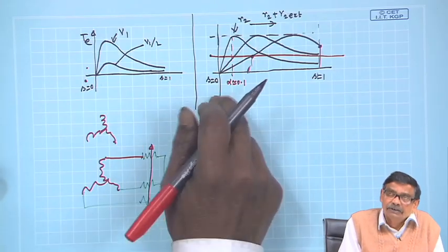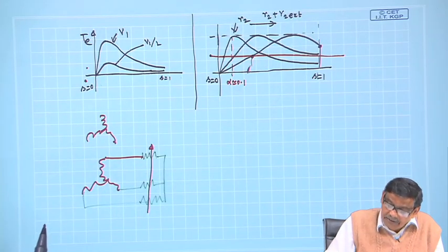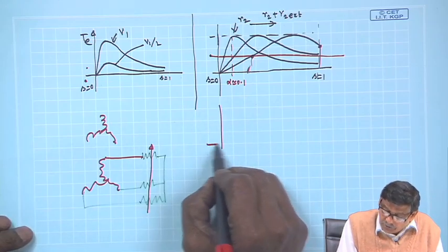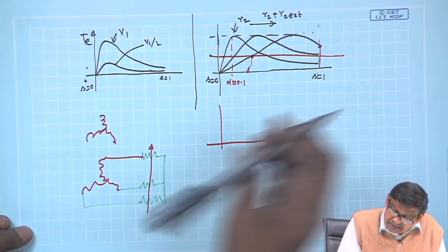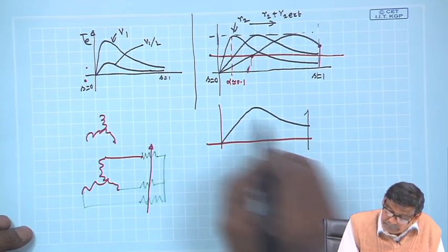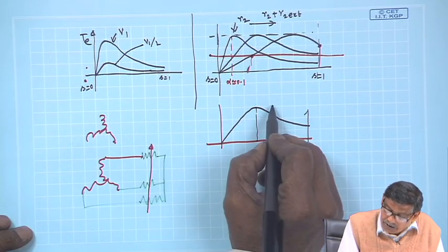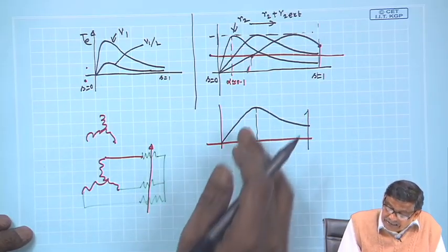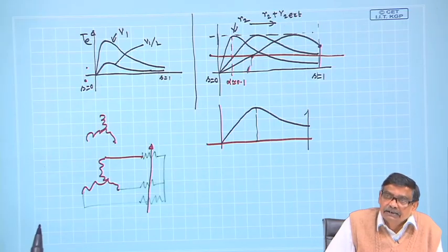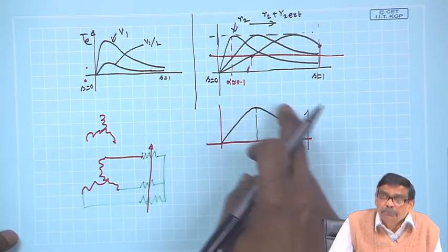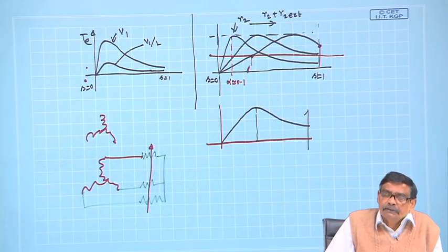This number is decided based on that. Suppose somebody designs a machine whose inherent rotor resistance is such that T max occurs like this, then we are talking about an induction motor whose rotor resistance per phase is higher, and therefore, such machines will not be that efficient.